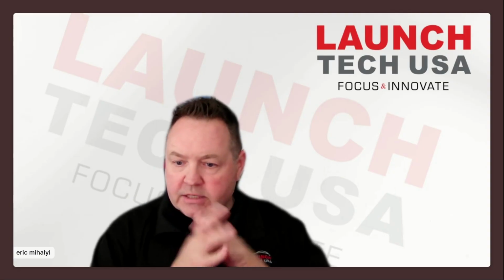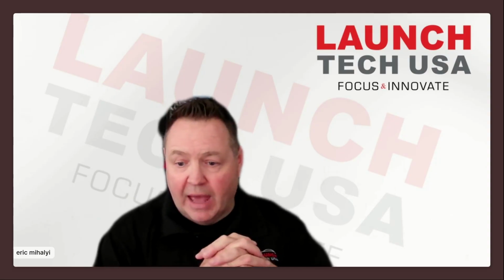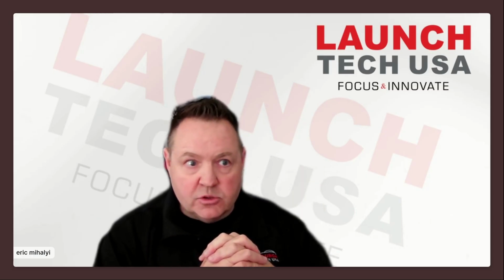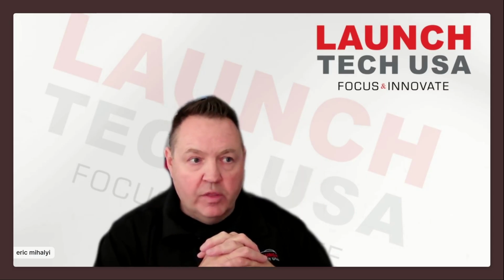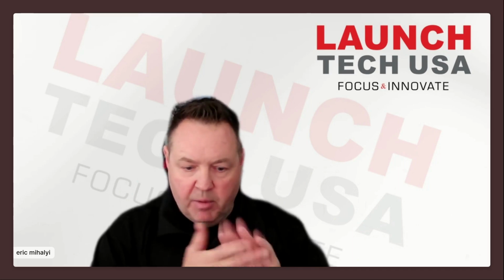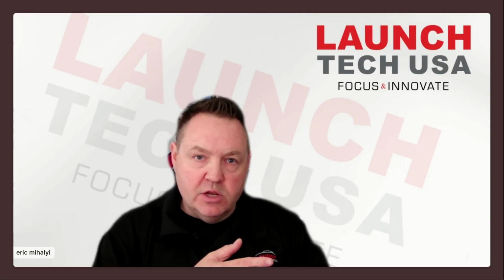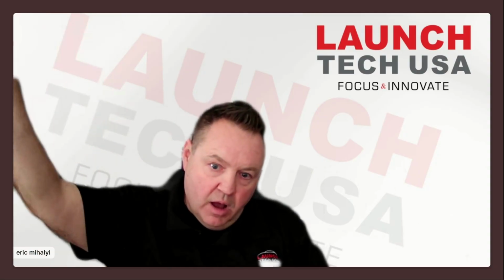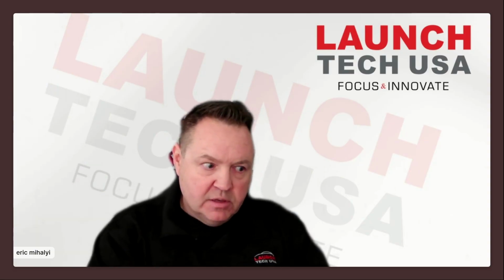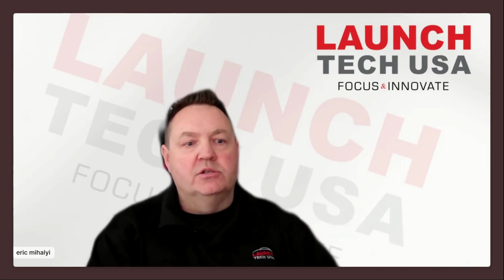So, Charles, I see you asked, do you require separate authorization like auto access? Yes, you do. That is Stellantis's thing. That is not scan tool manufacturers. Like I said, all these OEMs are doing it their own way. How they get in, some of them, it's being active to the internet, and the very first thing you do is contact a server in the cloud, and there's a handshake that happens. Yes, this is a professional tool, not a hacker, and it lets you into the car.